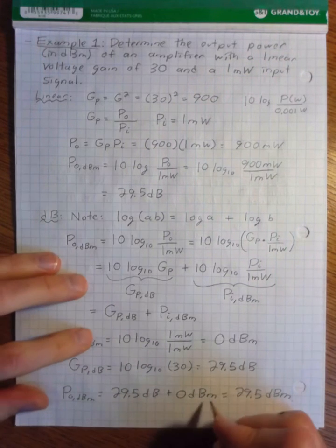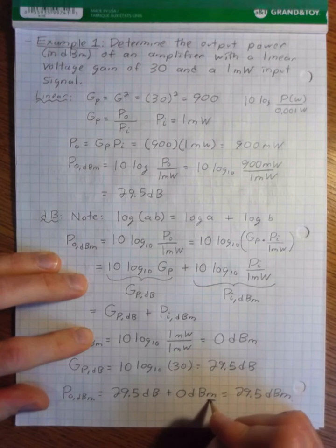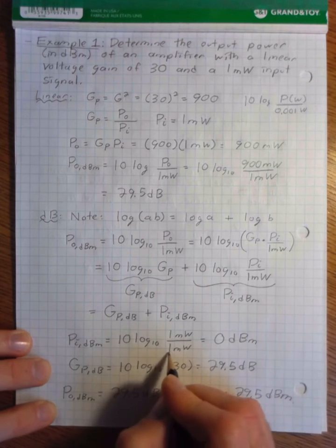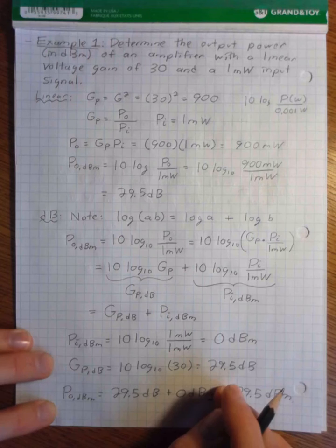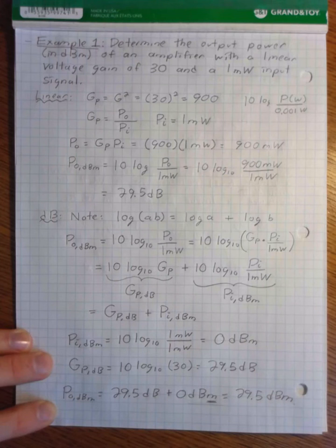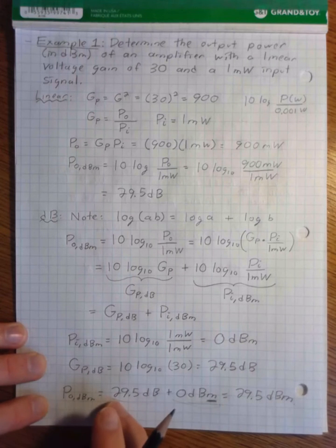basically this M here is just a little placeholder. It's just a reminder that we've taken the decibels relative to a fixed reference power level. However, dBm is still just a plain old decibel calculation. So essentially, this has units of dB and this has units of dB as well. This M is just to remind us that we've taken the power in dBs relative to 1 milliwatt, but the unit is still in decibels. So basically everything here is decibels. This is just a little placeholder reminder for us.